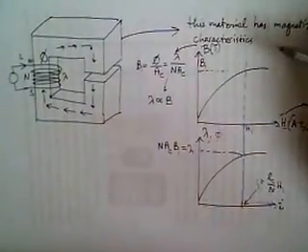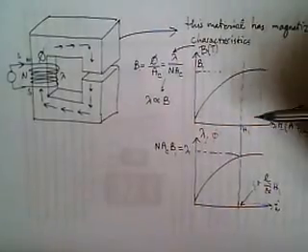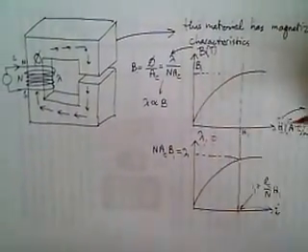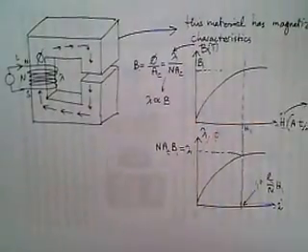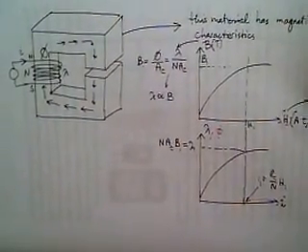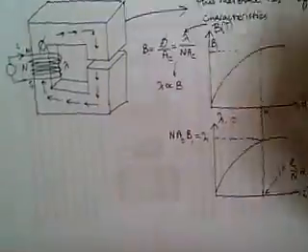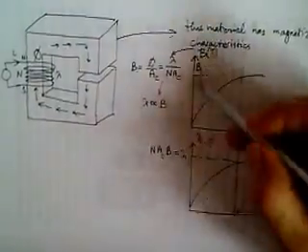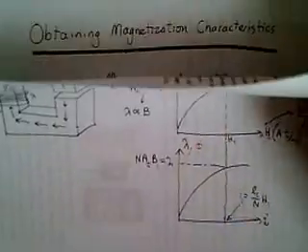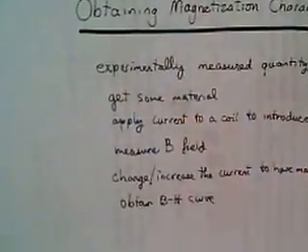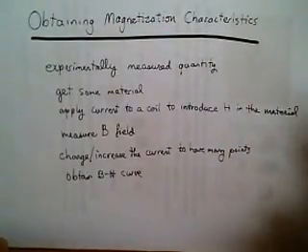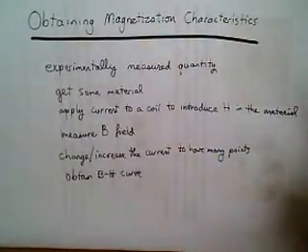In different resources, we may see so-called BH curves or lambda-I curves, and they actually represent the same thing, but with some proportionality constants. So the curve shape does not change, only axis values change. To calculate magnetic stored energy, we need those curves.